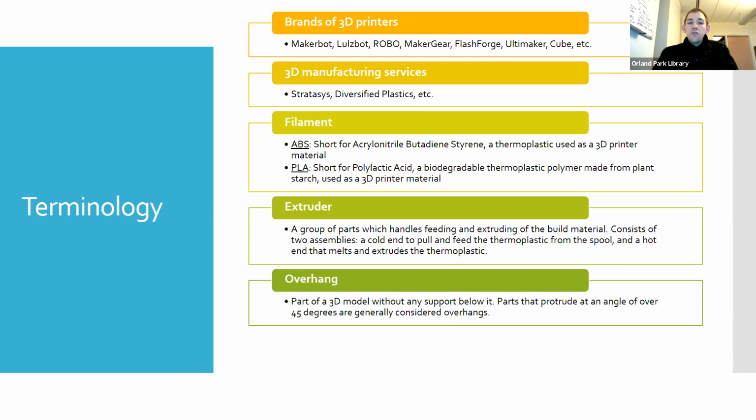And an extruder is a group of parts which handles feeding and extruding of the build material, and it consists of two assemblies: a cold end to pull and feed the thermoplastic from the spool, and a hot end that melts and extrudes the thermoplastic. So what that is...